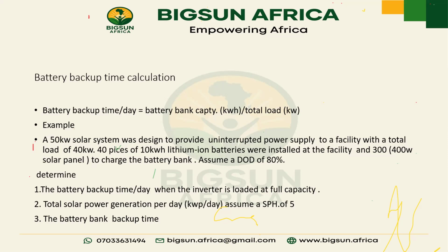So let's say I'm a 9 to 5 person, which means I have a routine. If I leave around 8 a.m., I'm coming back around 4, right? So when you want to make a design, you follow the pattern at which the person is using the light and know the time when the battery will start working. For a person like me, by the time I start using much of the power, the solar is already gone.